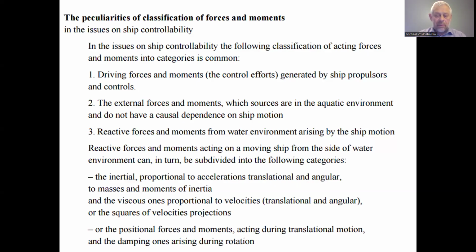But the hypothesis of linearity is required to have the analytical solution of the differential equations. So the viscous ones are proportional to velocities, translational and angular. The category of viscous forces can also be proportional to the squares of the velocities, but likely to the velocities in the fourth degree.